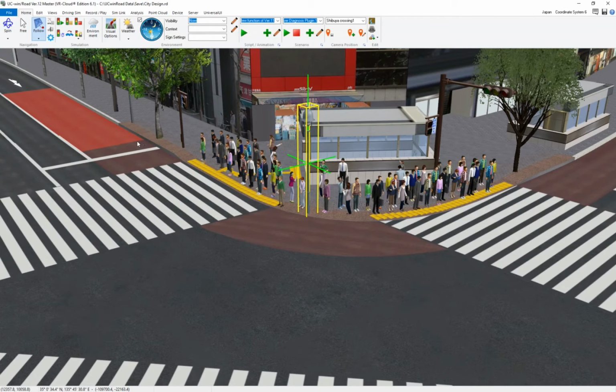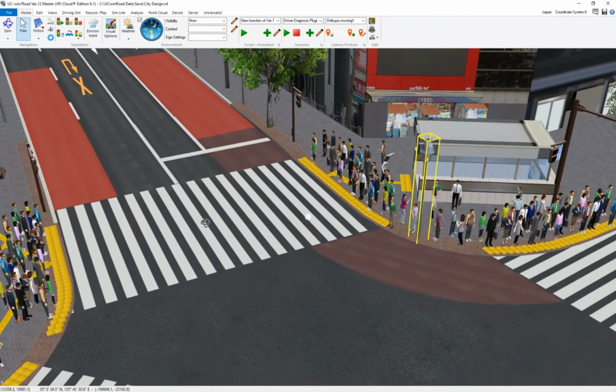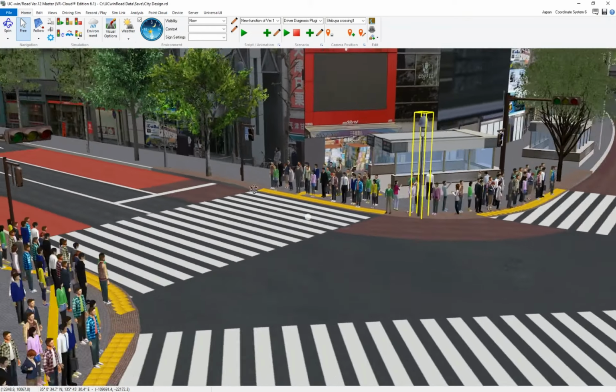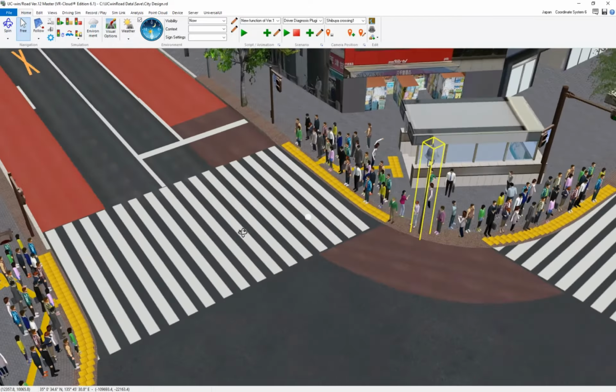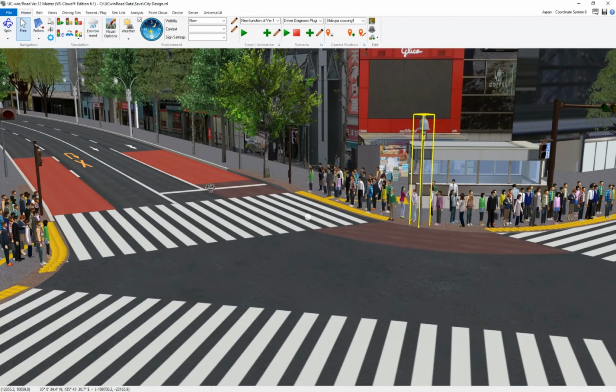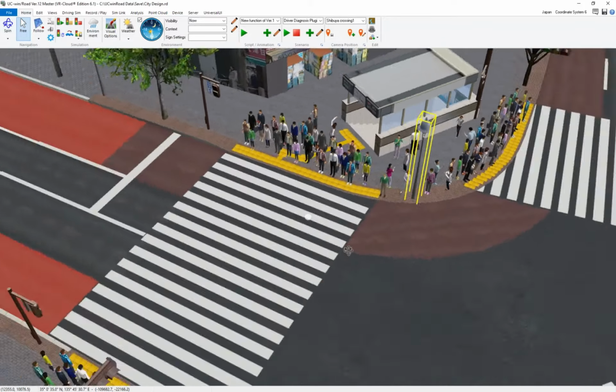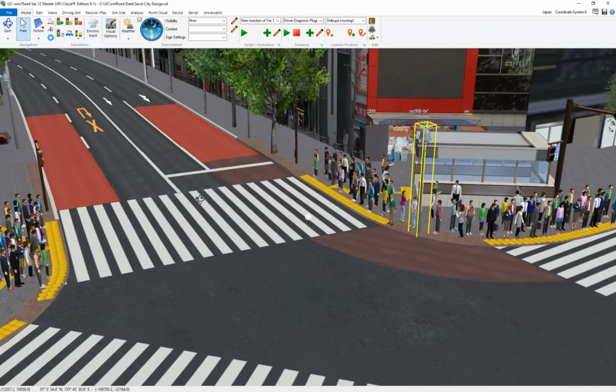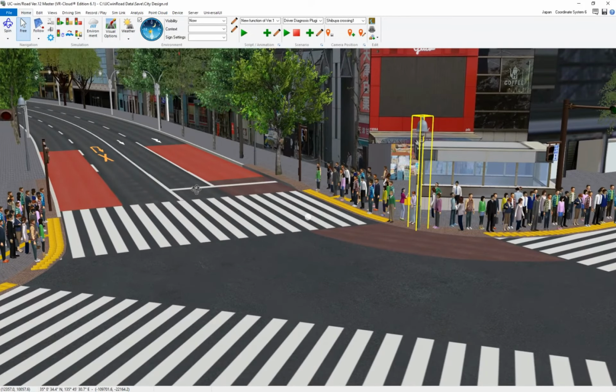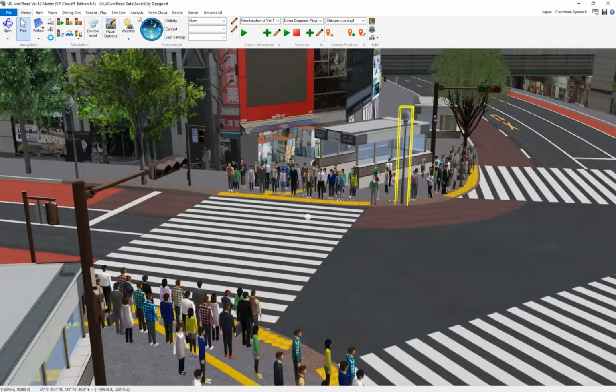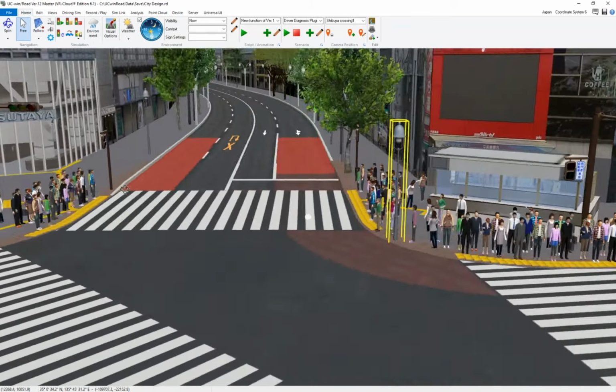There is a spin mode also available without selecting an object. For this you have to right click anywhere in the scene and it will rotate around that point as you keep the right button of the mouse pressed. So if you right click, keep the mouse pressed and drag around, you will actually move around the point you clicked on.